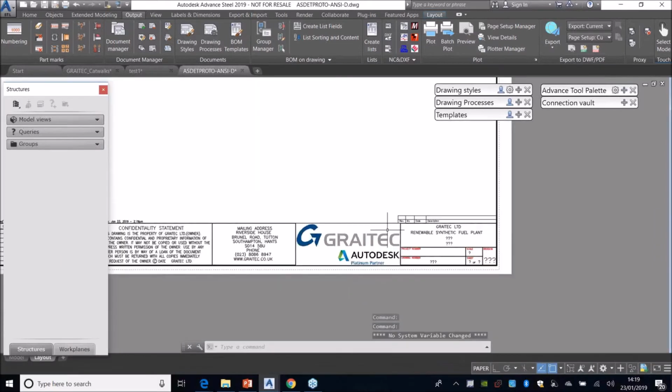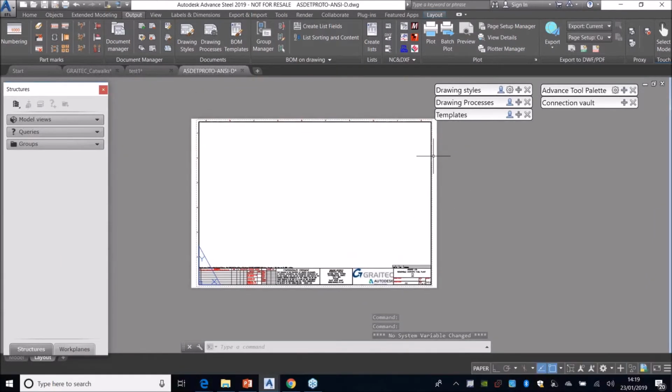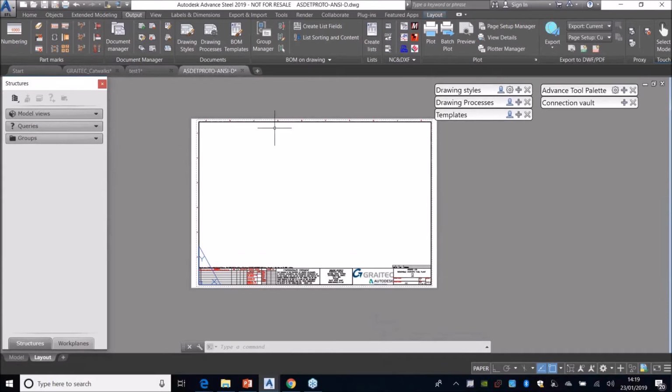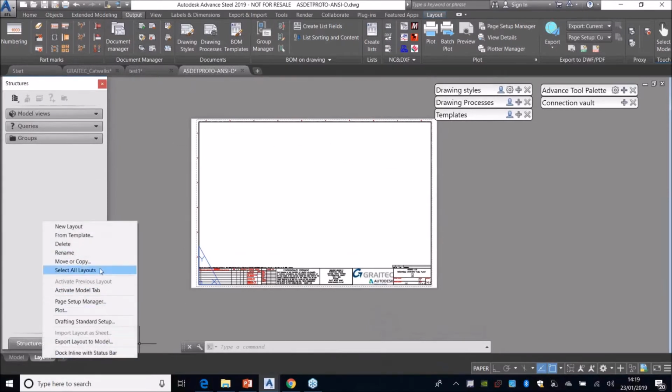Okay, so it's a given that you'll want to have a different header and a different look to the frame to replicate their standards. Well, let's talk about the dim style settings in the CTB file. So the CTB file, of course, is going to be dedicated to each individual prototype file. So this is actually pretty easy to manage.